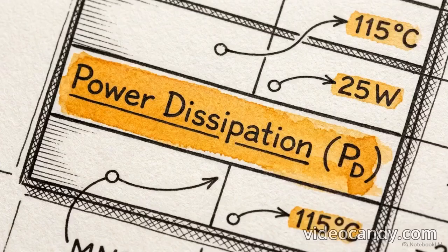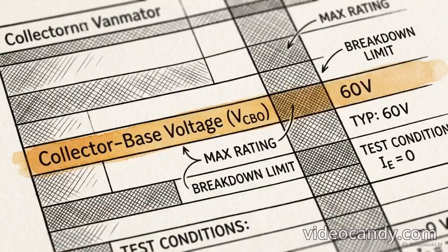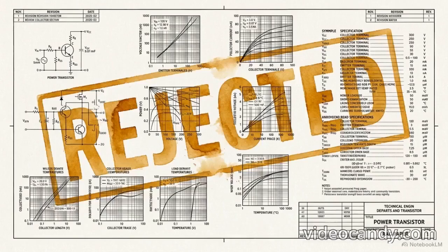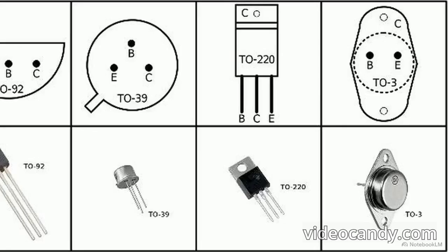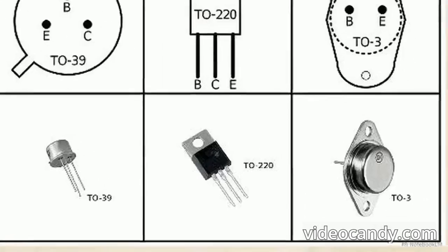Mathematical gain is irrelevant if the physical material fails. A theoretically correct common emitter amplifier will break down immediately if the design violates the hardware constraints of the silicon. These constraints are hard-coded into the manufacturer's datasheet. Designers must verify maximum power dissipation, absolute maximum collector current, and the reverse breakdown voltages before permanent damage occurs.